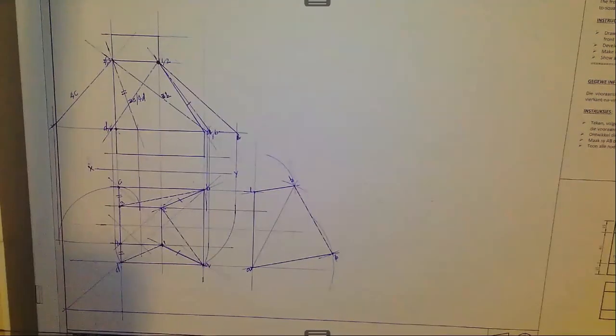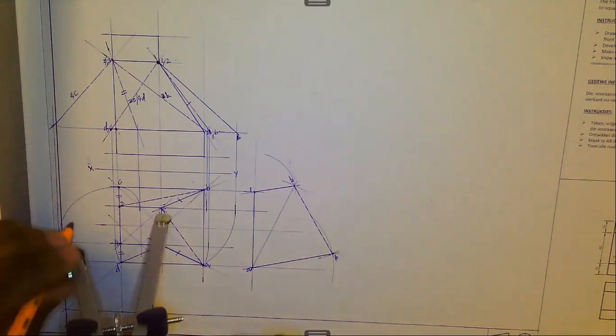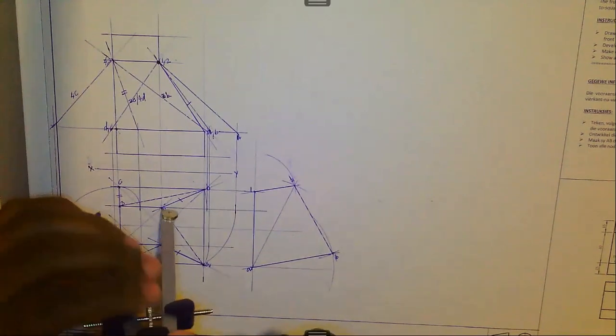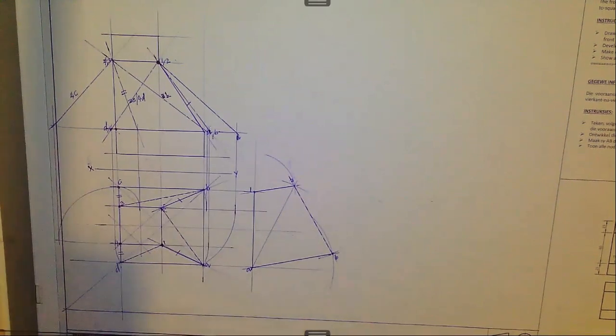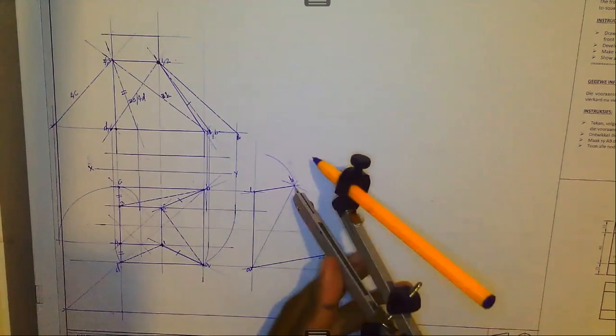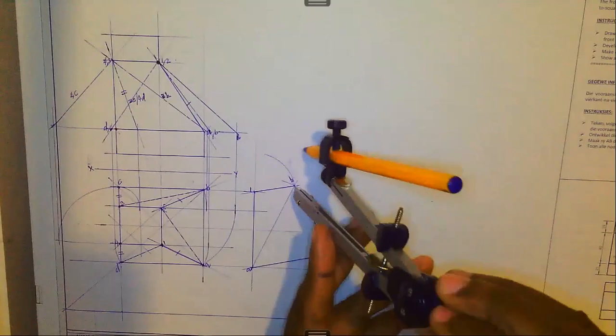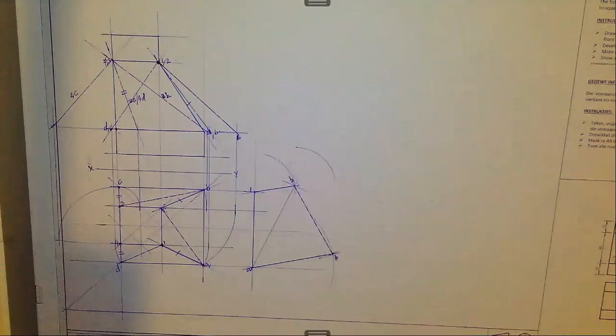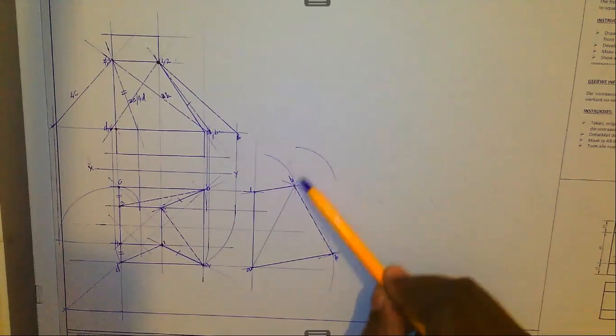The next point that I require is point number 3. Remember, 2 to 3 and 2 to 3, in both views they are seen parallel to the ground line. So what it means is that this is a true length. Like I said, if you have got that detail, you can forget about going up there. But this is only applicable if you really know that what you did first is correct, because it would have a cumulative effect in terms of an error. So somewhere on this arc would lie point number 3.